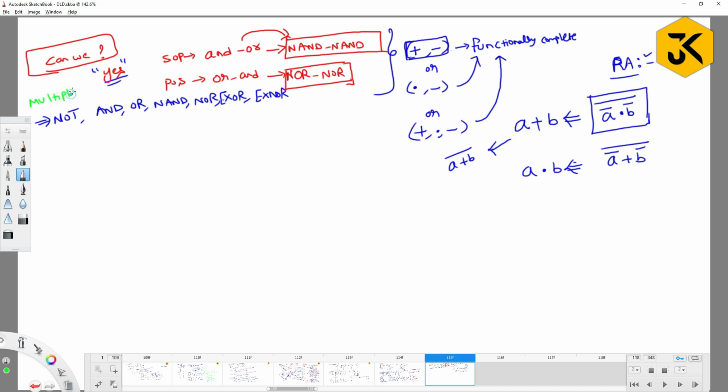So here, to prove that, I can say that multiplexer is functionally complete. That is the advantage. Multiplexer is functionally complete. That's the reason we can construct any kind of circuit, so that's why I am trying to do this example. Let me have a 2x1 multiplexer. What are the inputs here? It should be S0, it should be Z, and it should be I0 and I1.